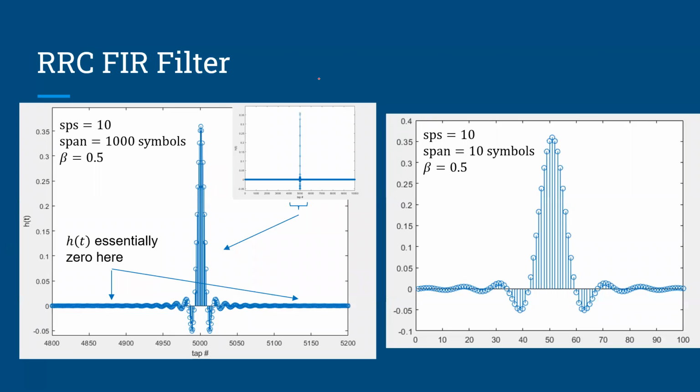So in this case on the right here, this is a total of 10,000 points. And you can see at the center, you get the actual filter response. And at some point, it basically dies down to 0, but not exactly 0 because it's an infinite impulse response filter. And then I zoomed this down to this guy. And so that's what the center looks like.